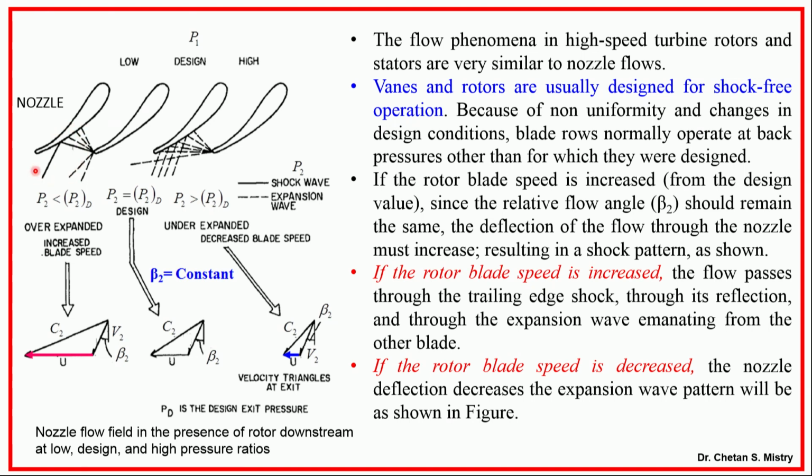Now, what is happening? Suppose I consider my rotational speed to be lower. Under that condition, my exit pressure will be greater than my design pressure. If this is your situation, you will have your expansion fans placed here, and that is what gets reflected.